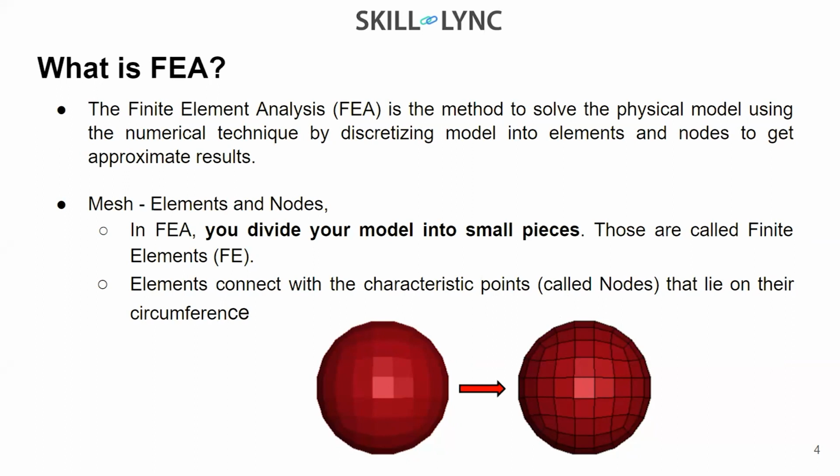This is a prerequisite to go ahead for any study of a component or any type of study in FEA. If you don't have a mesh, you can't go ahead. You must know the types of mesh qualities and everything, which again we are going to cover over here. Elements also have characteristics. So what are the elements? Elements are the smaller geometries which capture your bigger geometry. Like you can see a sphere over here, right? That sphere is captured with the help of smaller elements.